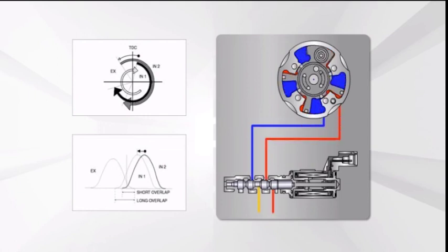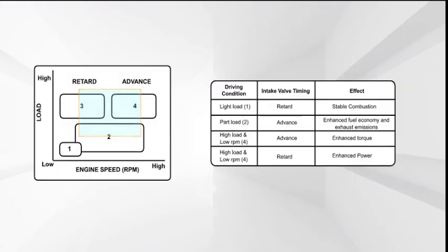Rather, EGR is used under acceleration, except WOT, and part throttle conditions. The orange box outlines the EGR operational programming of the PCM and for the EGR monitor. EGR is not always needed, but in this highlighted area, CVVT via communication from the PCM does perform actions to affect an EGR effect, which in turn reduces NOx emissions to levels of control by the catalyst. WOT is not a consideration for EGR because at this demand the driver is needing full power even though combustion chamber temperatures are at their highest.